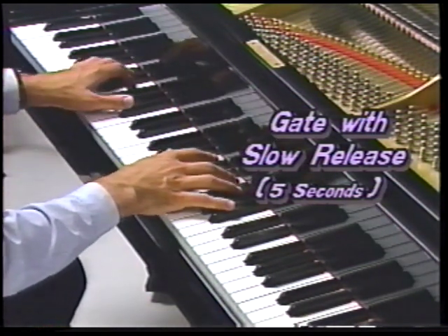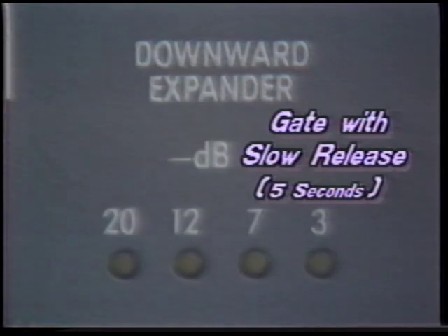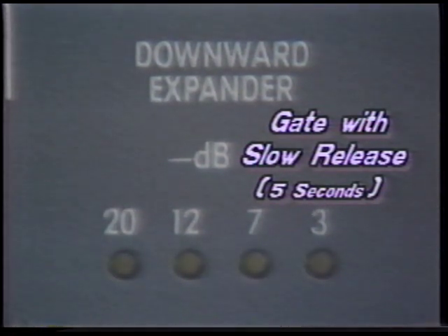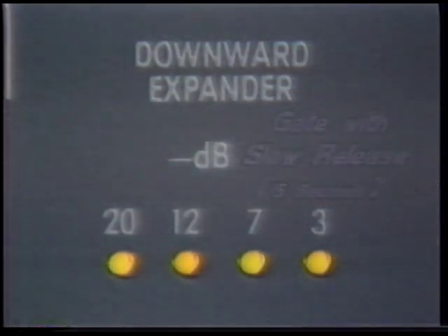A fairly slow release time will let the entire fluttering signal fall past the threshold point before it actually releases. In the case of something which has a very quick decay, you can live with a much faster release time.